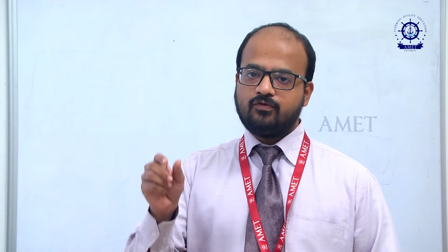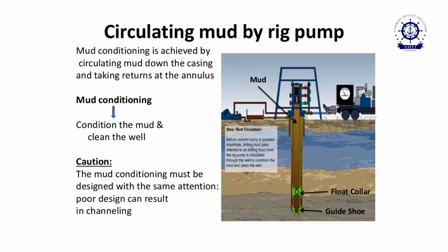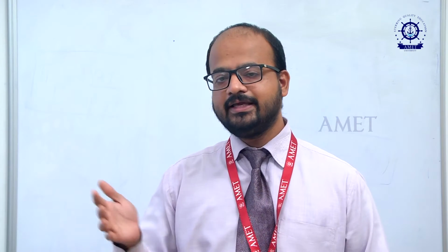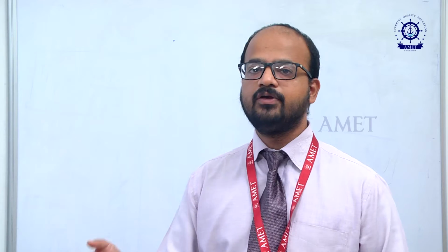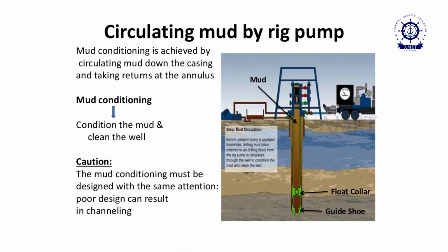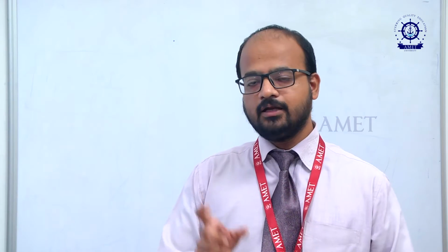So if it is like that, and directly I put cementing inside, again in the annular space or side of the well bore, it cannot be mixed together, because the chemical already exists. That chemical is coming from your drilling fluid. It becomes like cake. Again if I put cementing, what happens? It cannot be mixed together. For that purpose, we have to first completely clean up all those mud cakes.